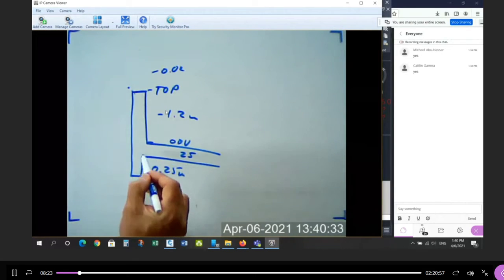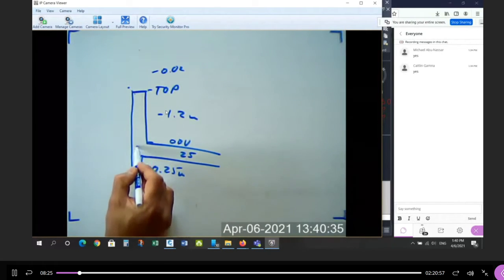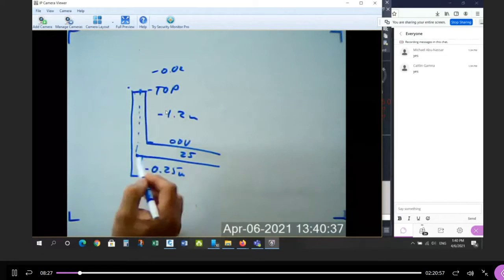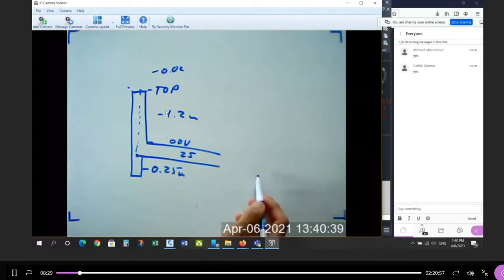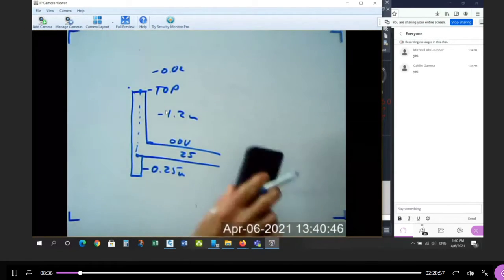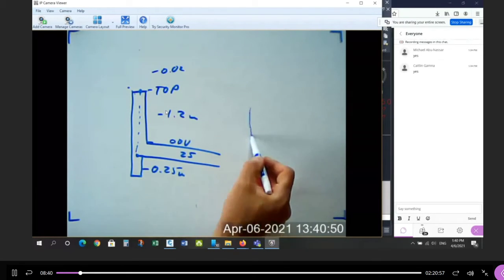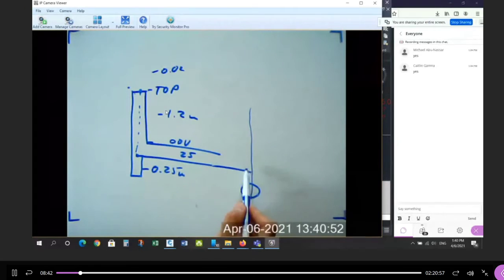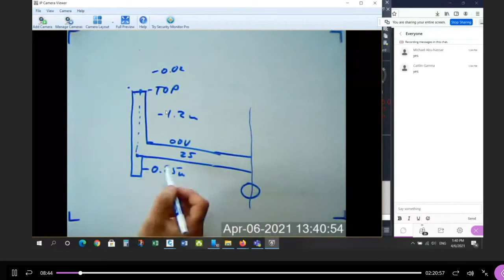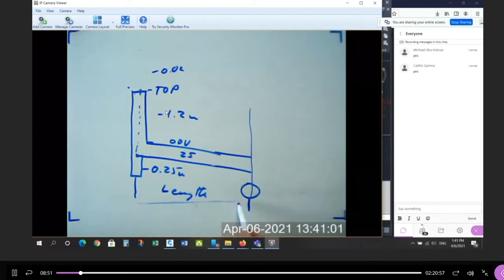And we do that calculation actually at the center of the structure, right? From the center of the structure to the center of the structure. When we get to the street, we take it to wherever the center of the pipe is. That's a bad drawing. It should be bigger. All right, so the street pipe, I just extend, think about the center line of the pipe. I just extend this pipe until it hits that. And that's the length from the center of the structure to the center of the pipe. That's the total length. And it's a plane distance. It's horizontal, center line length.